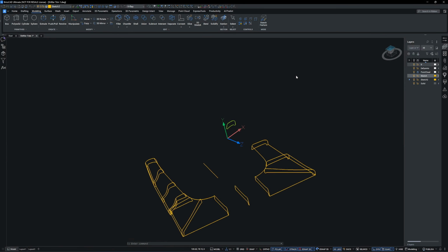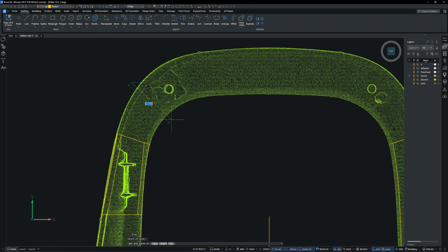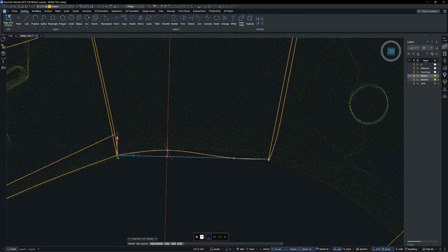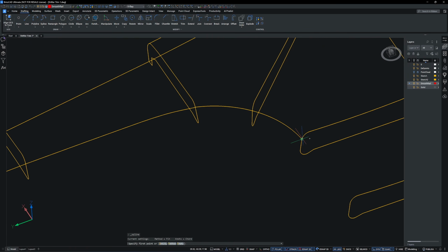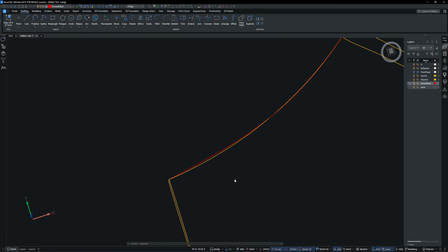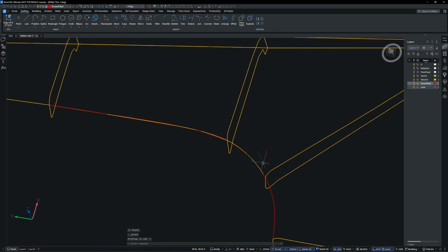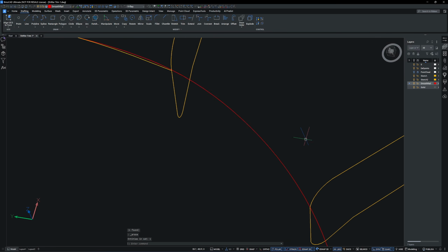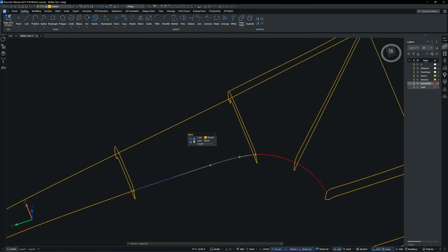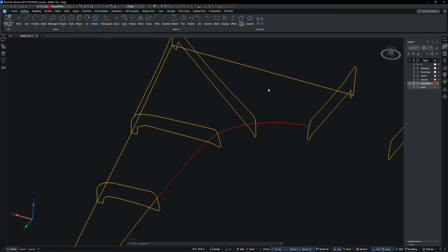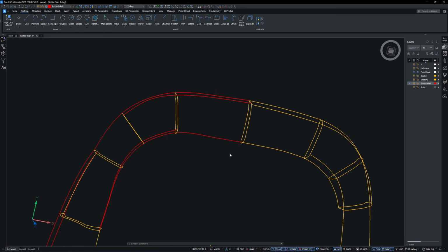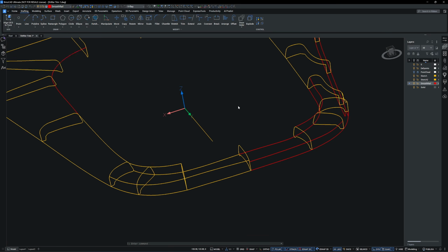When you place the cross-sectional sketches closer together, the surface comes out smoother and is less likely to show faceting. Now I have finished all the sketch cross-sections. The guide rails were created in segments and they are not tangent from one to another. So what I will do is retrace them as a continuous spline and then break it at the boundaries. The broken spline will keep its shape and tangency across segments. All the red lines shown here are retraced splines.